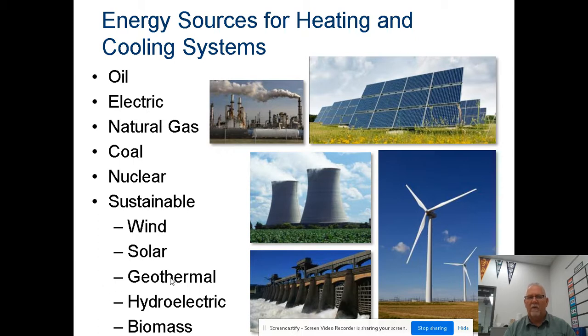Geothermal, the idea of that, we use the underground temperature to keep our houses warm. Thinking of geothermal, the temperature under the ground is usually, you go down about 6-7 feet, and the temperature is about 50-55 degrees. Where geothermal comes in is if you have a hot day, if you have pipes down there and running fluid or air through the pipes, it's cooling it down to that temperature, then you can just push some of that into your house to cool it down.